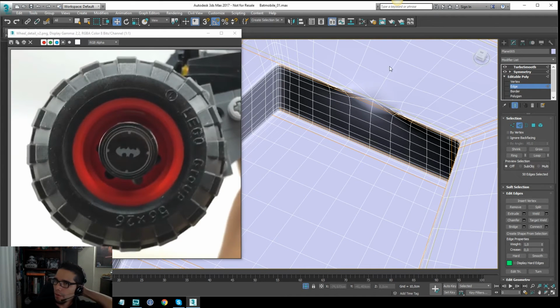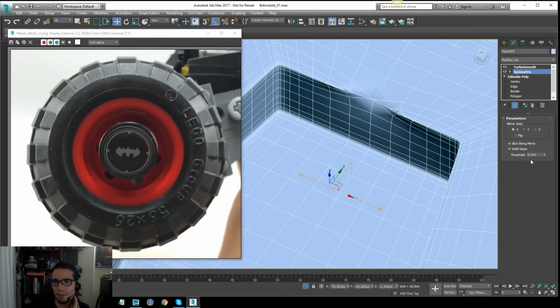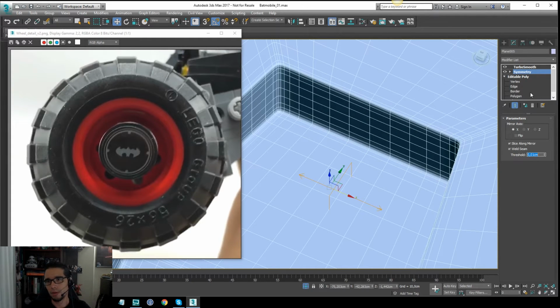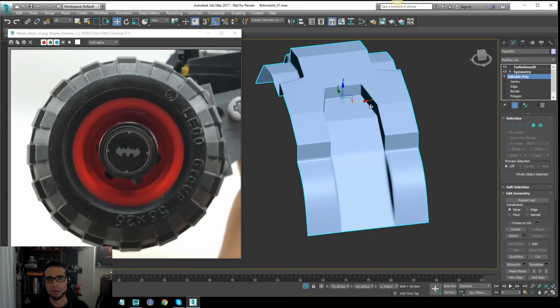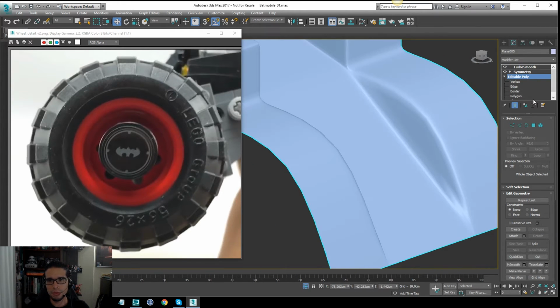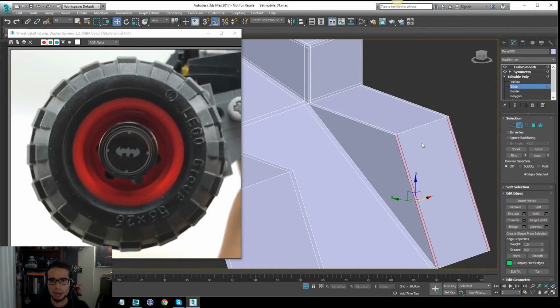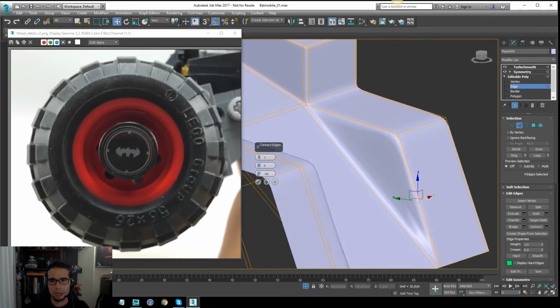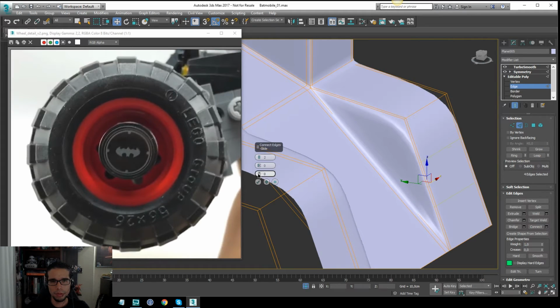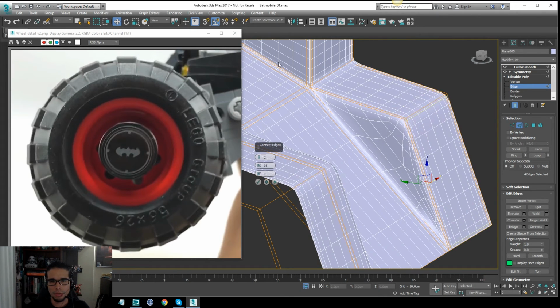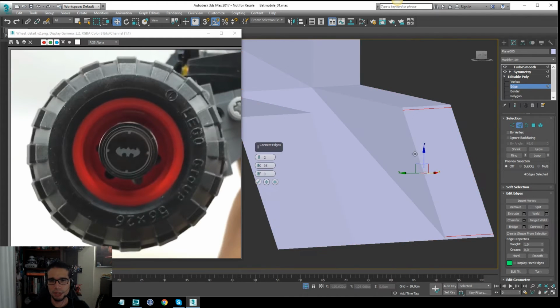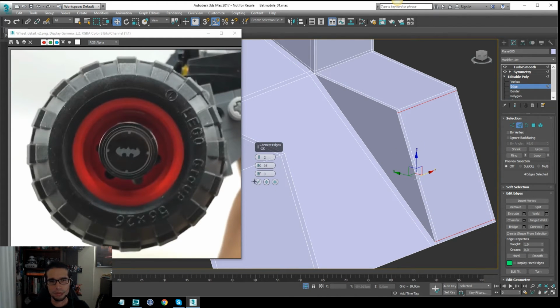Here I have an issue, I have a problem. This problem is related to the symmetry modifier, because the scale of the symmetry is a little bit big and is welding a couple of vertex, but right now it's fixed. So right now I have almost everything. The only thing I need is to have a sharpened vertex here. So in this case I am going to connect. I will not use two, just one, and I will move this element nearby the top, and let's verify how it looks. So you can see here it looks good. I will see how it looks with the two subdivision. Yeah, I think it avoids a little bit of stretching. I think this works good for what I want.